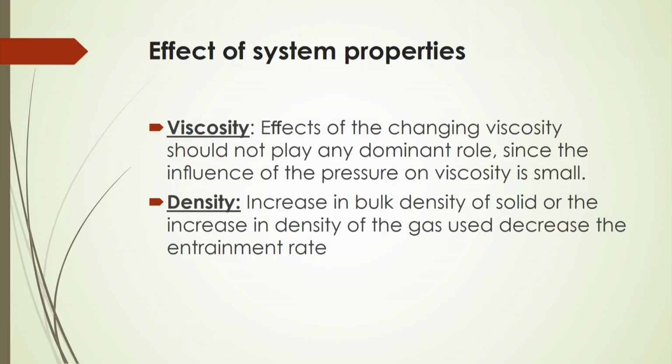The effect of changing viscosity should not play any dominant role, since the influence of the pressure on the viscosity is small. An increase in bulk density of the solid, or an increase in density of the gas used, will decrease the entrainment rate. So, the density factor is very dominant here.